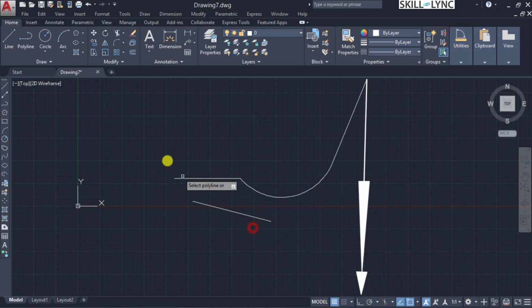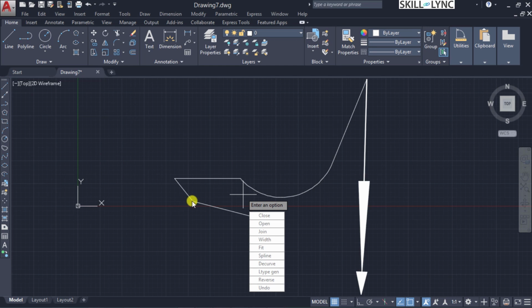So let's select these two lines for multiple. Select this object, convert to polyline, use the join command, and let us use the same command, but this time let us use both the options. Let's see how the object is merged. So for the same fuzz distance of 50, you can see that it has added one more segment. So instead of extending, it uses the add command in order to close the polyline. So this is how your join command is going to work based on the different join types.